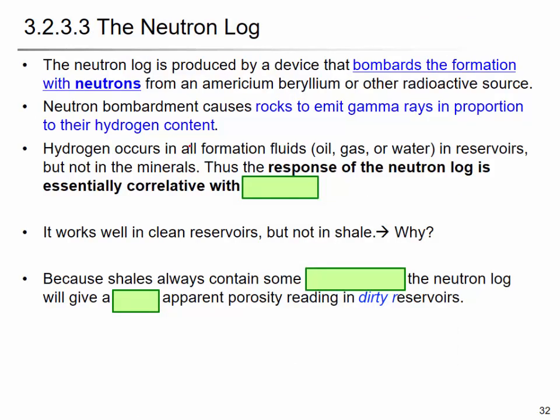And the neutron log is more common, and that measures the number of neutron particles when you shoot the formation with some radioactive source. This neutron log is the same as the densometer that we use for the pavement. So when we check the compaction or the dry density in the field, we bring some equipment, right? That's the neutron densometer. It's the same principle.